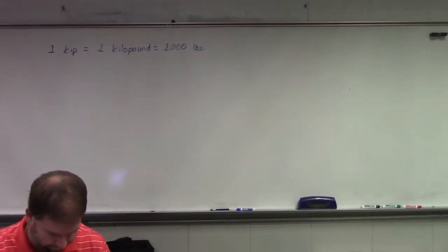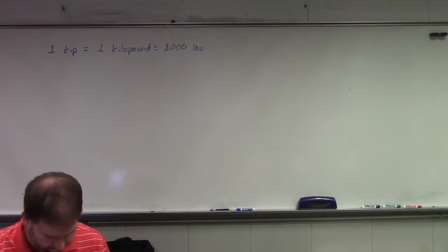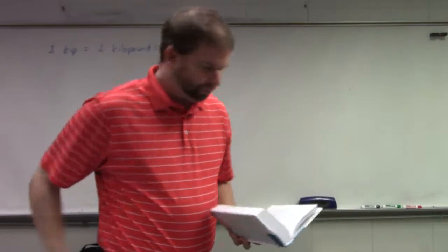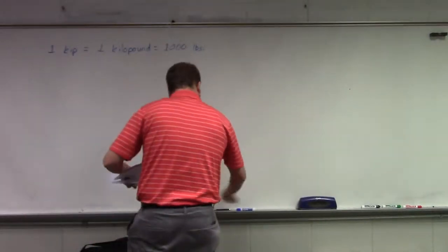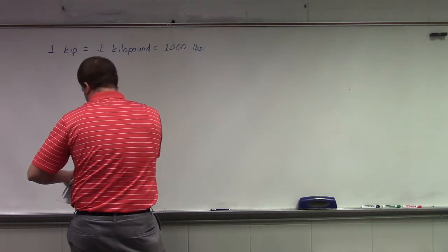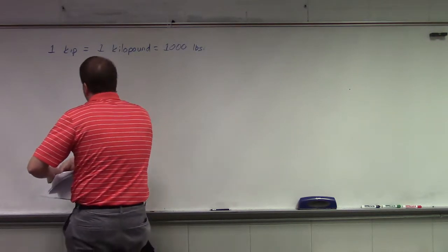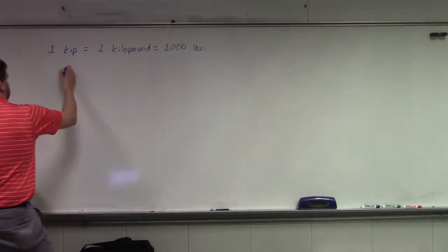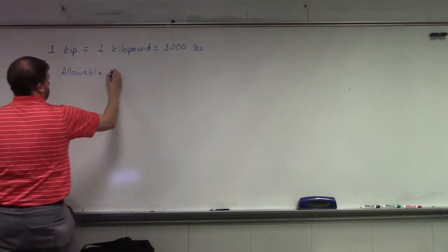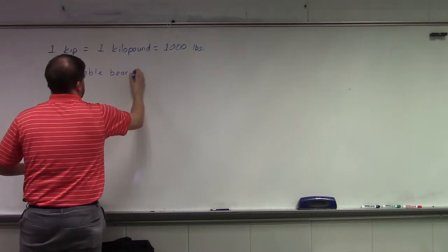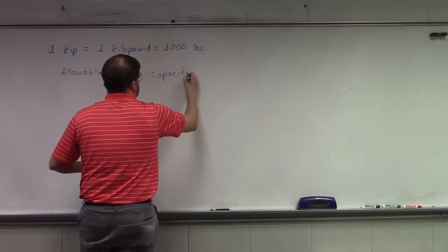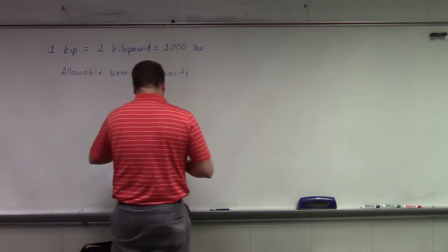So, on page 51: the allowable compressive bearing capacity of a soil is 8,000 pounds per square foot. What should the length of a side of a square footing be if the total load, including the weight of the footing, is 240 kips? So that would be the F equals P over A formula.